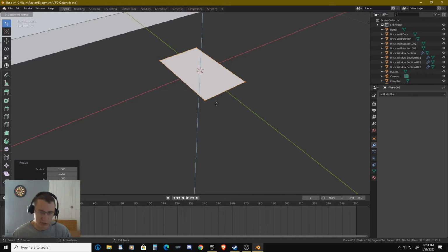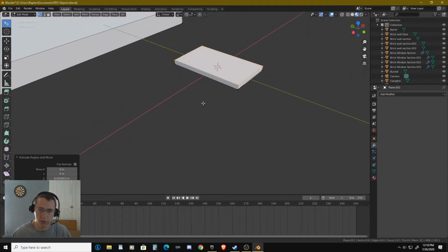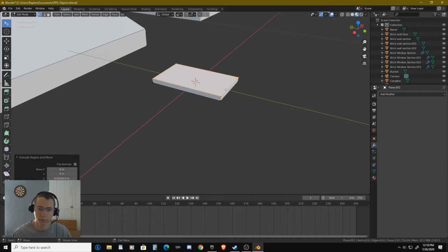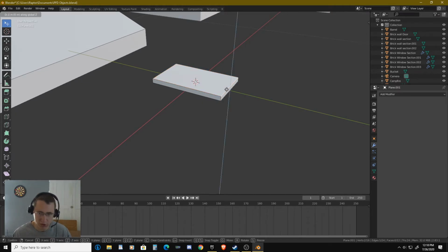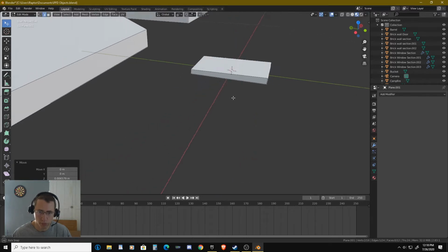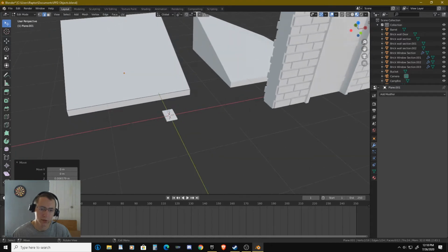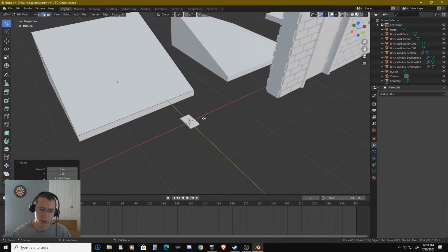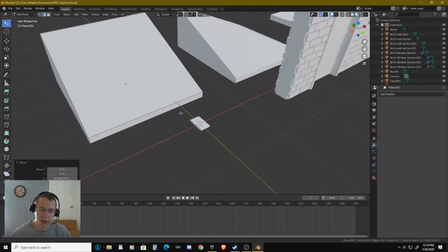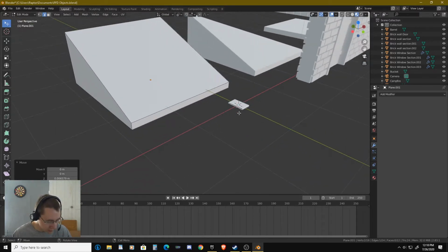So we're going to extrude this one, and we're going to turn off snapping so that we can just get the thickness that we want, and we'll do a shingle. There we go. And I'm going to bring this edge up just slightly, so that's just slightly thicker on one side. We'll nail through this side into the roof, and then this side will be for the outer edge. Okay, so I'm going to go ahead and deselect everything.